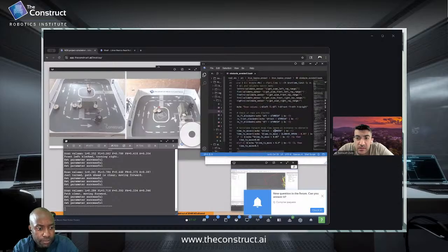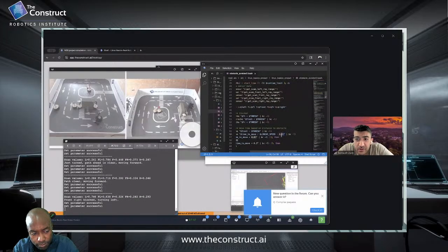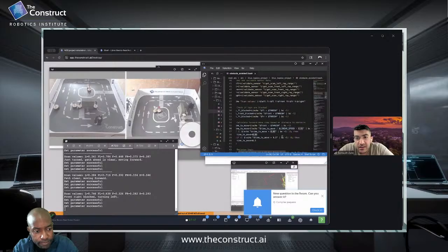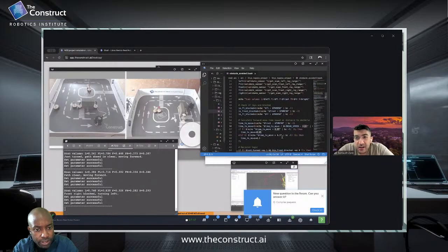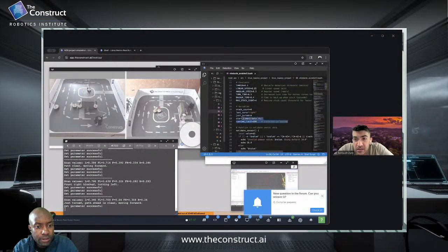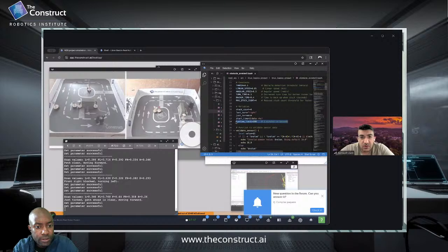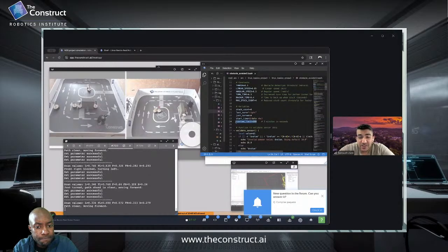It's the front distance minus the threshold that I set, divided by the linear speed, minus some margin, just to have a clear path so it's not going to overlap. All right. And also the whole simulation is about 5 minutes. After 5 minutes, it is going to stop everything. So I think it's necessary to have something that keeps the robot in the loop and continuously working.